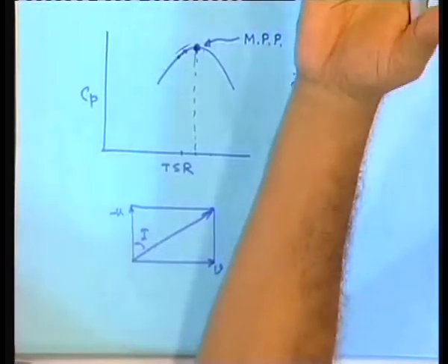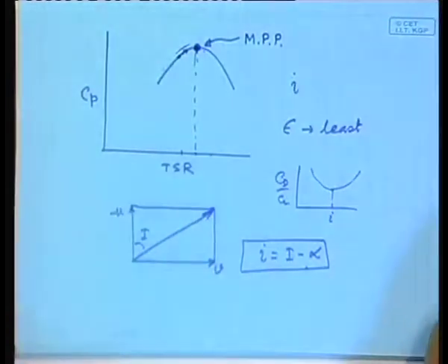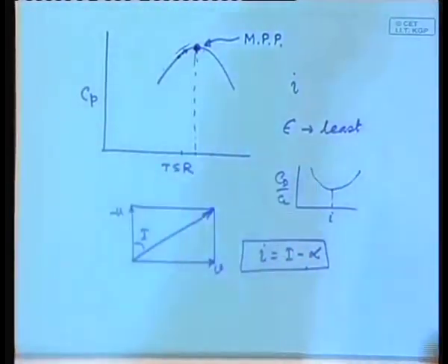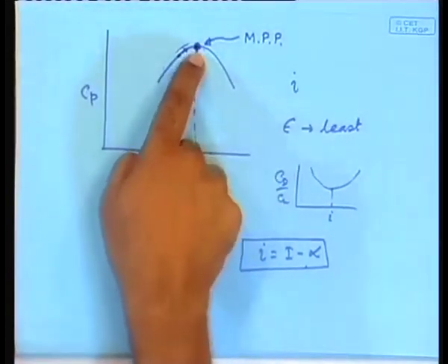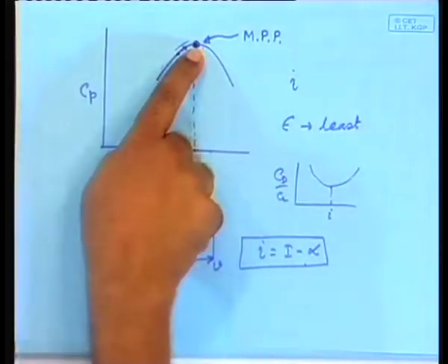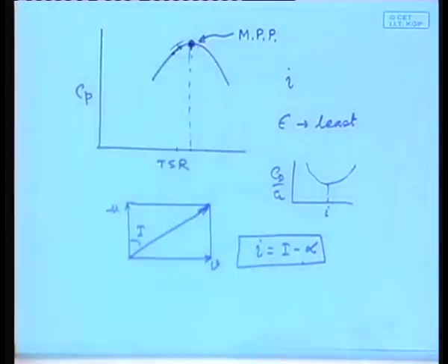Now, just build this as a continuously checking logic. That means, if the wind speed changes, everything changes, the speed has to be changed, the pitch angle has to be changed, fine, but ultimately it will again get back to its maximum power point by the same logic. At the different wind speed, it should again check, am I working at this point? That means if I change my TSR now, am I getting into this valley? So that is another logic by which this is done. Clear?